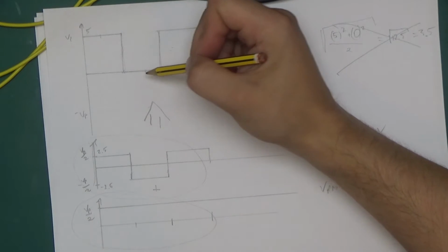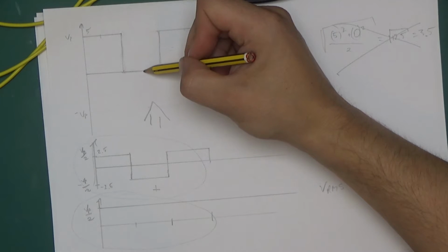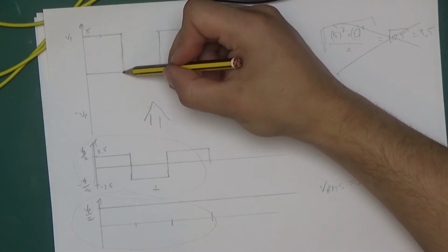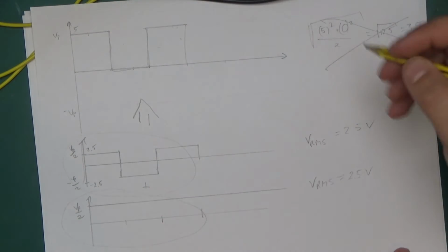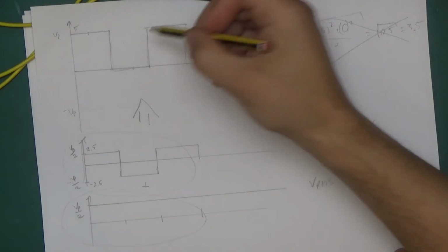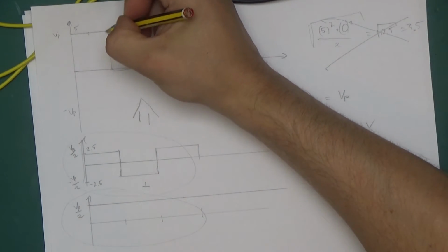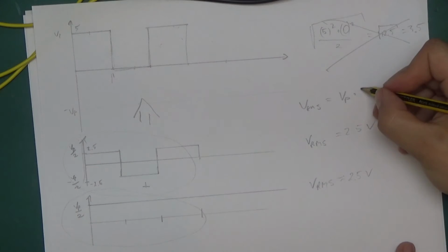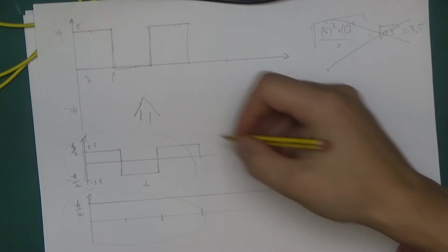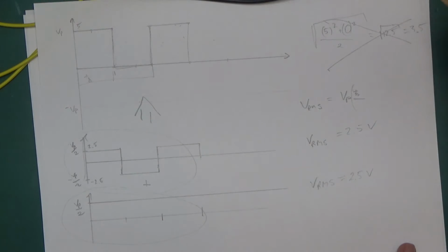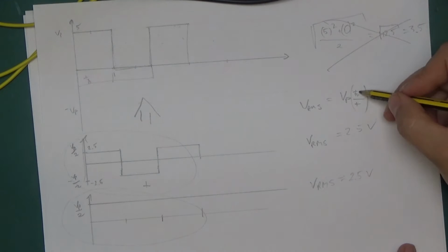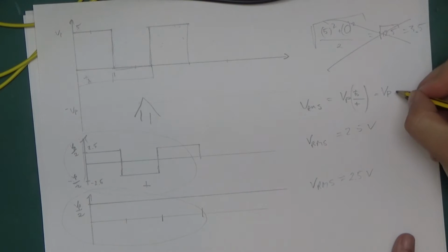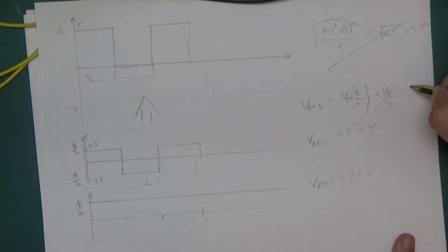With a positive square wave, what actually matters still, because again we are not going equally in both directions of the zero axis, is the duty cycle. In the case of a positive square wave like this, the actual RMS value should be the peak value, the high state if you wish, times the ratio of this time, let's call that T high, divided by the entire period of the square wave, so divided by T. This is the duty cycle or aspect ratio. In this case it is 50%, Vp divided by 2, so that will be 2.5 volts.